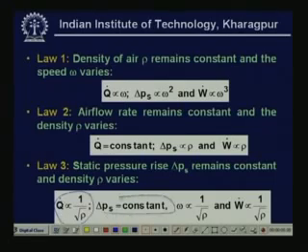So that is the condition of the law. And rotative speed also varies inversely with the square root of density. That is the reason why the flow rate also varies like this. And finally, the power input to the fan also varies in this fashion, 1 by square root of density. So, these are some typical fan laws.